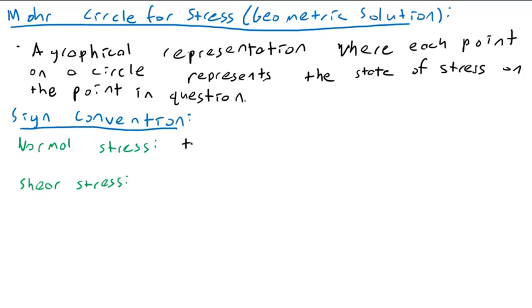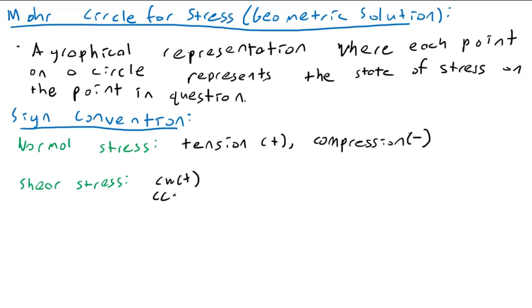This is just saying that tension will be positive and compression negative. Shear stress, we're going to use the convention clockwise is positive and counterclockwise is negative.